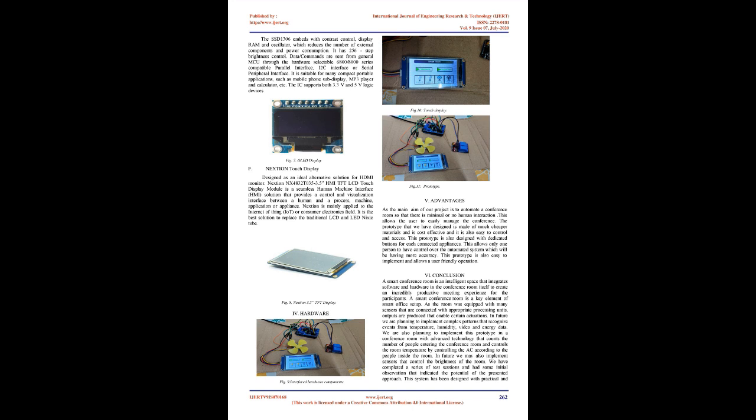The output channels of both the L293D chips are broken out to the edge of the shield with 2 5-pin screw terminals, viz. M1, M2, M3 and M4. You can connect 4 DC motors having voltages between 4.5 to 25 V to these terminals. Each channel on the module can deliver up to 600 mA to the DC motor. However, the amount of current supplied to the motor depends on the system's power supply.